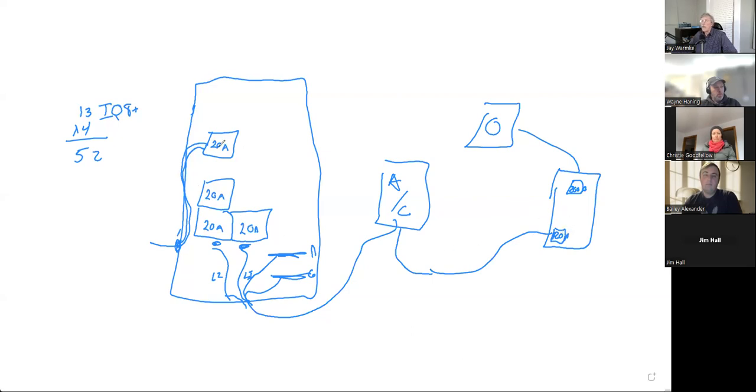Well, you've got a breaker here and you've got a breaker here. So that's your overcurrent protection. And in your AC disconnect, you might have a fuse. So that also is going to be overcurrent protection. But up on the roof, we're just going to go into a junction box. And then those are going to be under the solar panels.